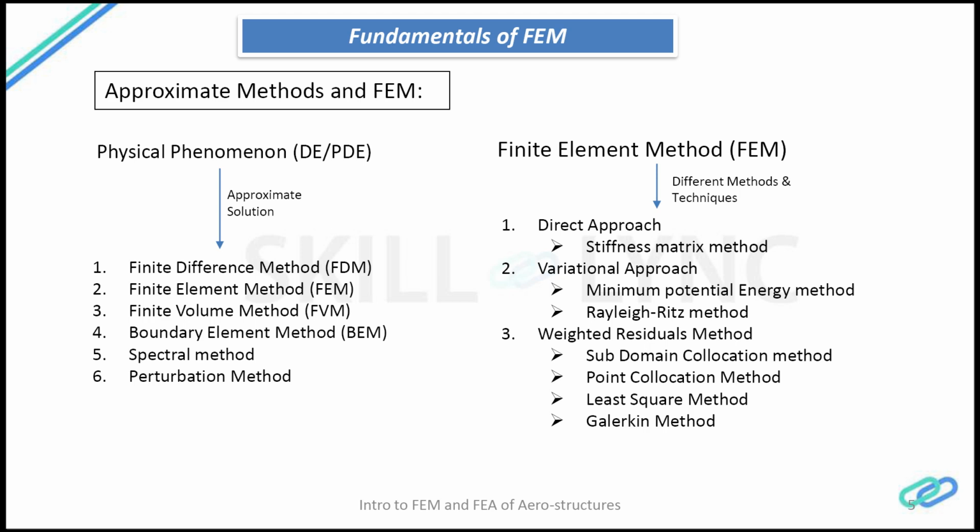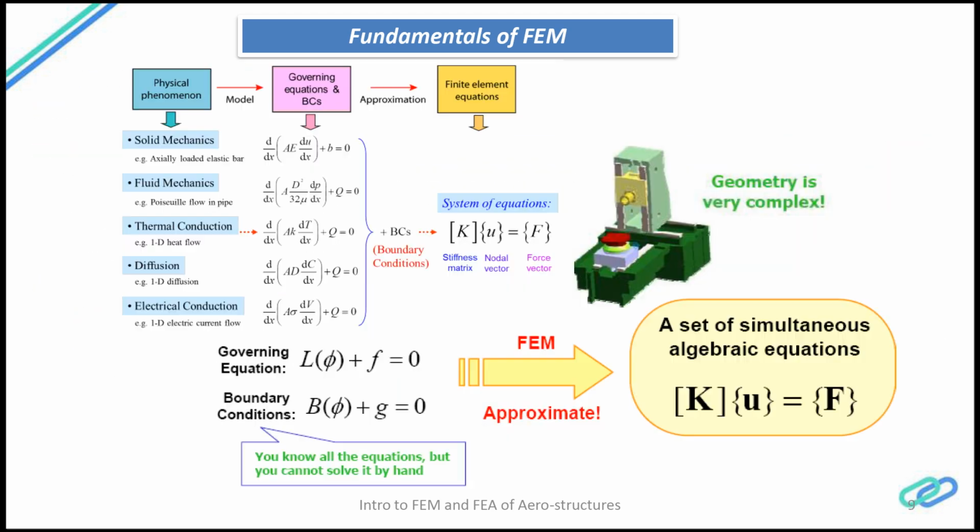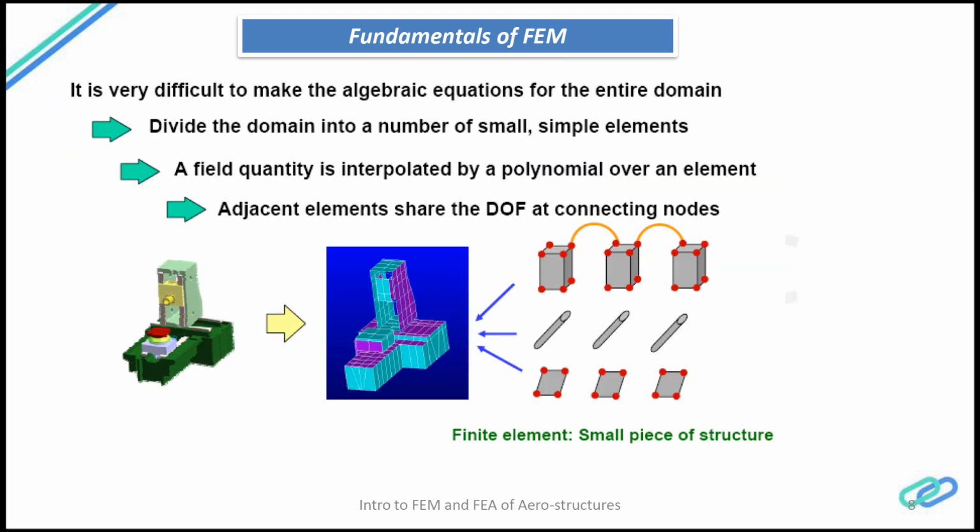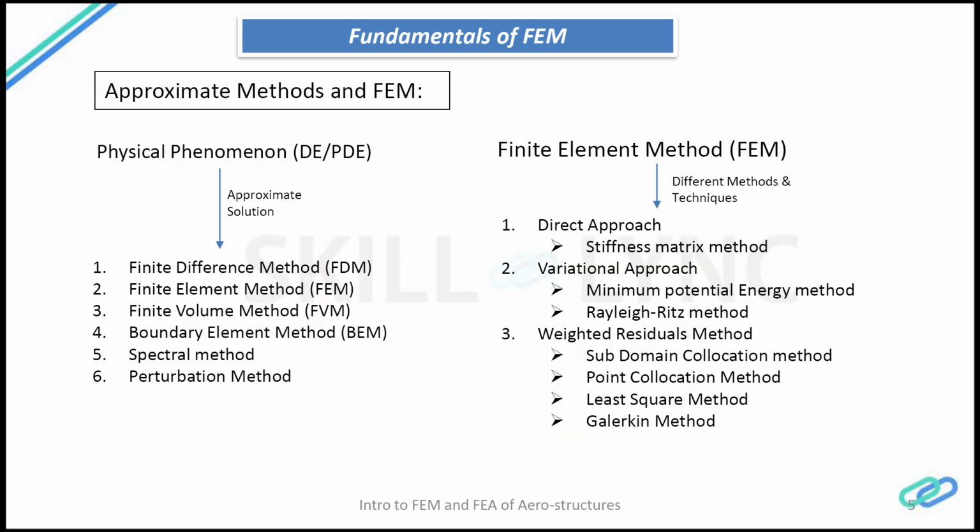There will be a mid node between the two nodes. Imagine a simple quad element here. The higher order element will have a mid side node, so instead of 4 nodes, there will be 8 nodes. So that's what I meant.